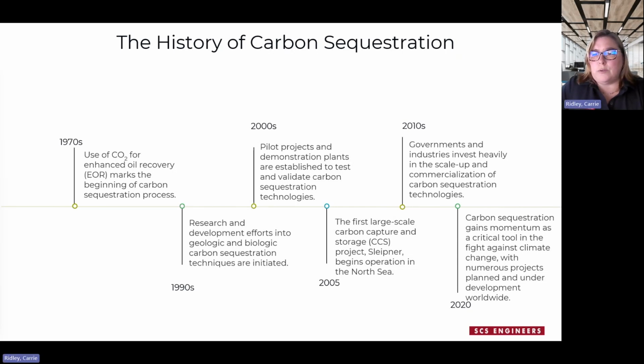The volume of CO2 pushes the oil toward recovery wells, and then it comes back to the surface as oil is pumped up. The CO2 gets recovered during the process. It gets skimmed away from the oil, and the brine that's recovered is stripped out and then injected over and over again until the field gets abandoned.